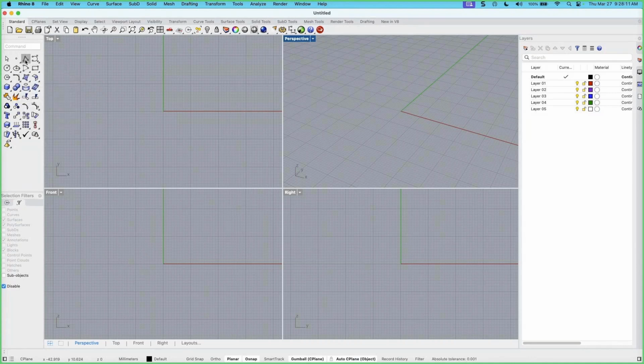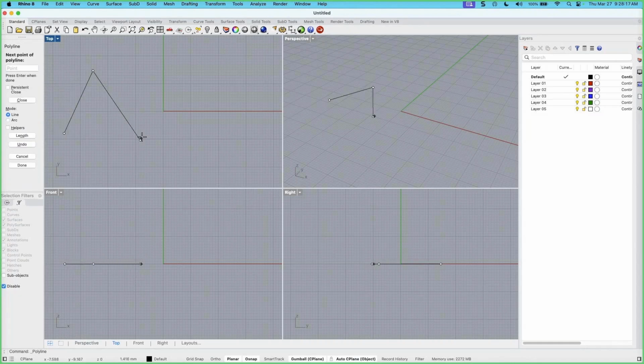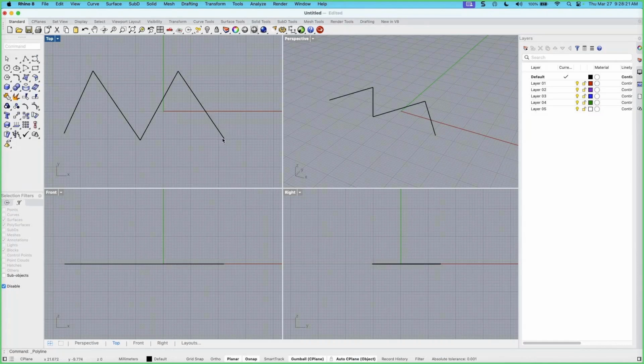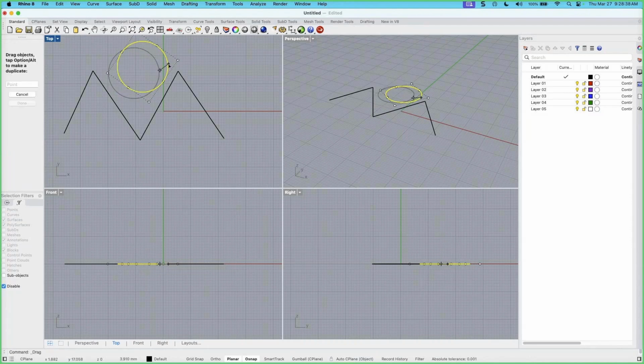And any command that you take will replace the sidebar with the command line. That's another difference from running on Windows: if you just take Circle, then that area of the screen becomes the command line. So I'm going to clear these modeling aids off just so we're kind of back to default.